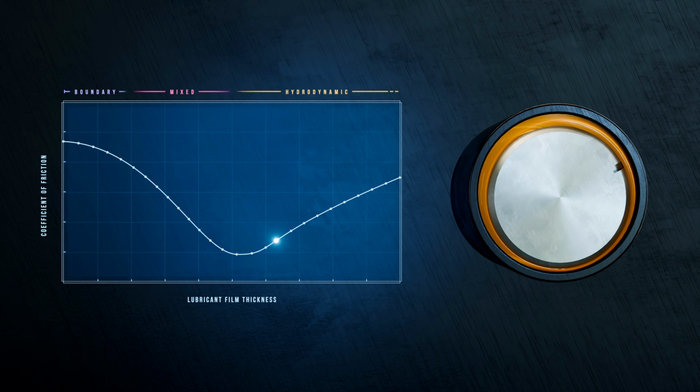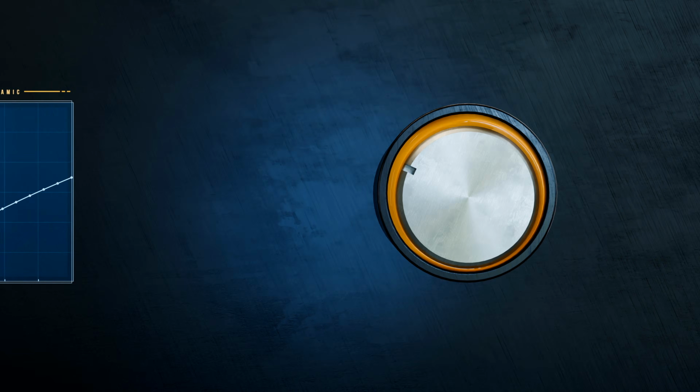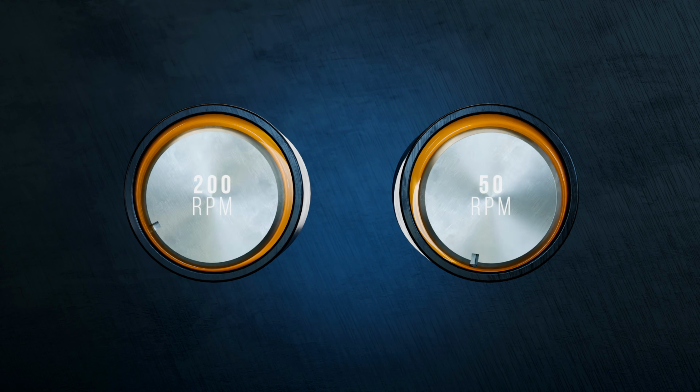Unlike dry contact, with hydrodynamic lubrication, friction tends to increase with sliding velocity. This is because viscous forces within the lubricant contribute most to the total friction force, and these forces depend on strain rate, which is determined by the relative velocity of the sliding surfaces.